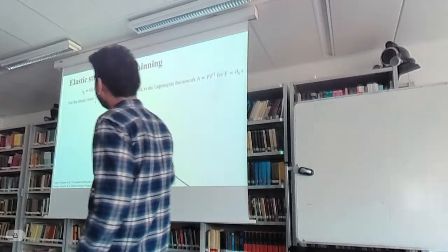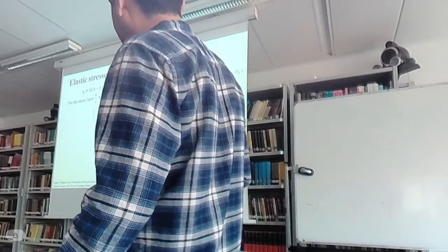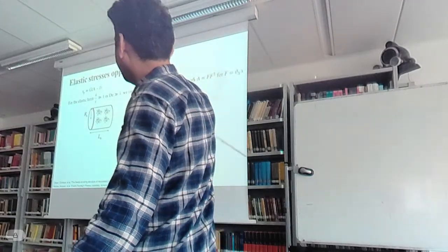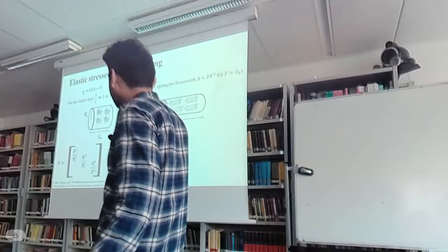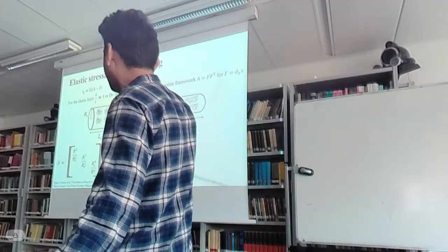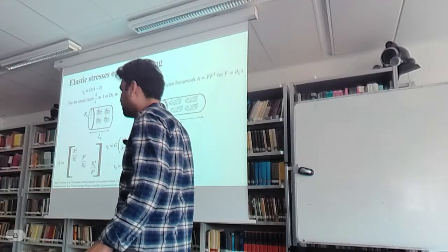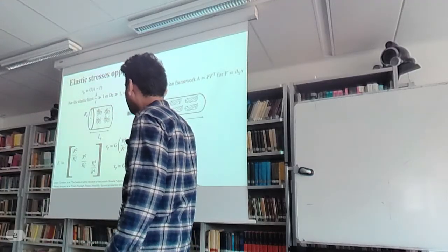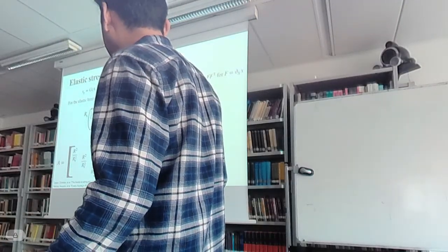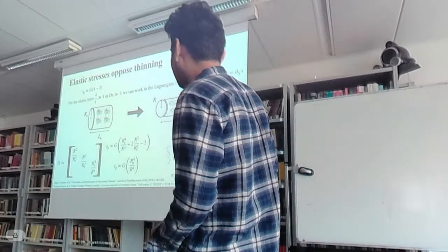So you have elastic stress, which is given like this, and you can again write the conformation tensor, but this time in terms of the radius of the jet, or radius of the ligament. So you get a conformation tensor like this, and you can get the stresses which are due to the polymers. And again, we have a fitting parameter here, which is Re, because there is again no equilibrium that we start with. And I assume that the jet is compressed much larger than the equilibrium radius. And then if you do so, you can again fit the stresses well from the simulation.